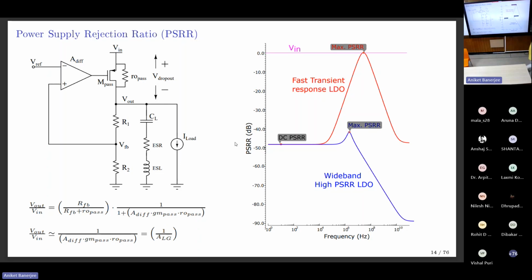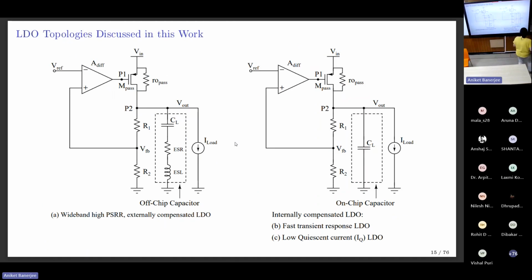Okay, so where we were: we started with square law. We said square law, let's throw it out. Then we said, okay, there is technology characterization that we can use to design a FET. Then we said that we understand LDO engineering. Now the next obvious step will be starting to design an LDO using technology blocks. So we'll walk you a little bit through that also. Here, we are discussing two LDO technologies, three LDO topologies, which we will characterize into two distinct groups.